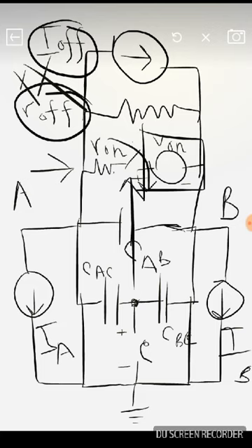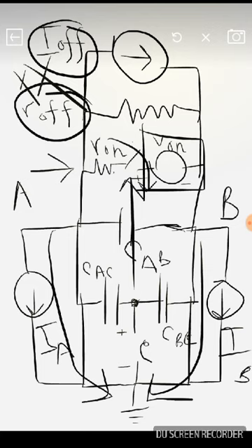This is because when a MOSFET is transferring data, some voltage is lost because of the charge feedthrough effect, which we will discuss in the next few videos. There is also a current loss, or a parasitic loss, that happens from A to the ground, and the same from B to the ground. We will explain how these happen in the context of a MOSFET in this video only.